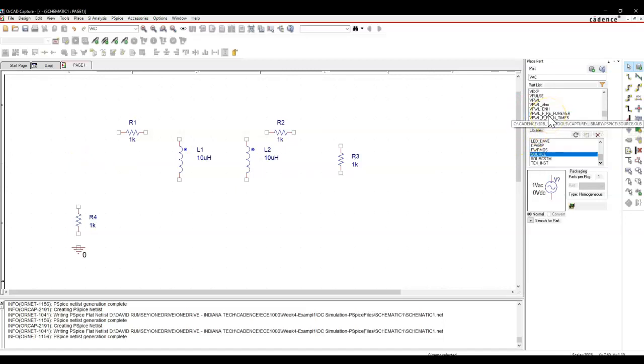In fact, what we want to do is, well, what I said is it looks like a sine wave. There's this V sine. That's what you always want to use for any kind of wall power or any kind of signal that's a sine wave, which is what we are going to use typically for AC signals. Now, that's not to say you would never use VAC. If we ever do a frequency simulation in this course, which I don't think we will, but if we were to ever do that, we would use this VAC. You'll definitely do frequency simulations later on in your curriculum here at Tech. So let's do the V sine.